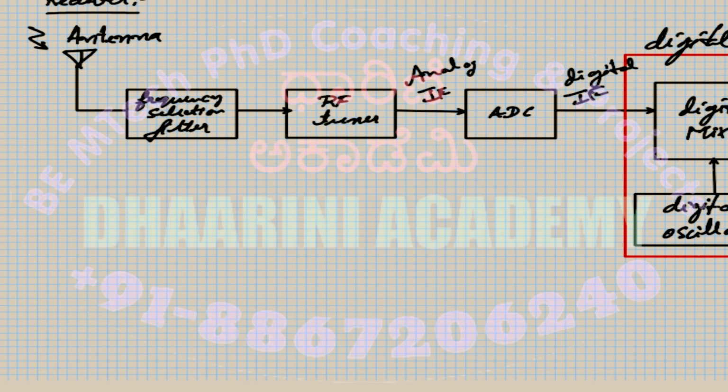You can actually change the modulation technique in order to bring security into the picture. If you use the software part here, the advantage is that all of a sudden the transmitter and receiver can switch their modulation technique itself. Let's assume that somebody is hacking the system and trying to intercept the transmission. What you can do here is randomly switch from ASK to say QAM. So nobody knows what you are using right now.